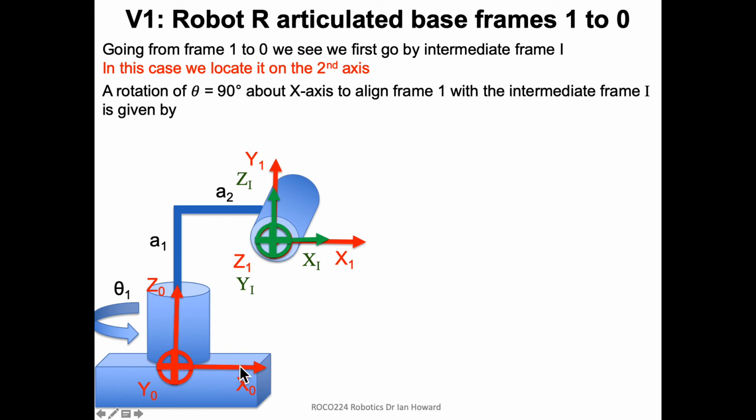In fact, it's rotating around x, in order to get, if we rotate this round, basically rotate it round x, z comes at us, right, and y goes up. So it's actually the mapping between frame 1 and frame 0 is also basically just a simple rotation around the x-axis by 90 degrees.